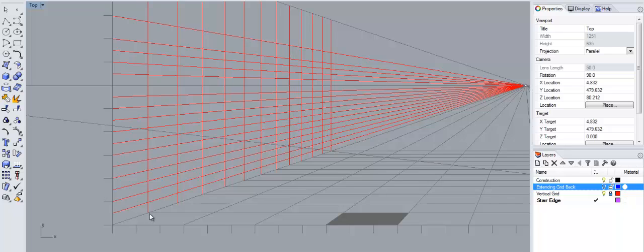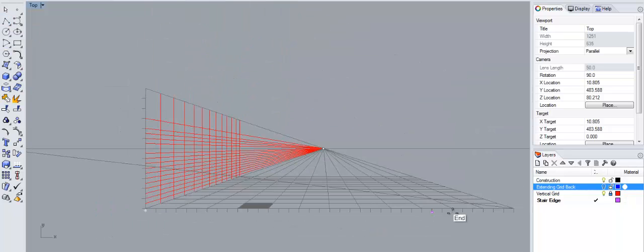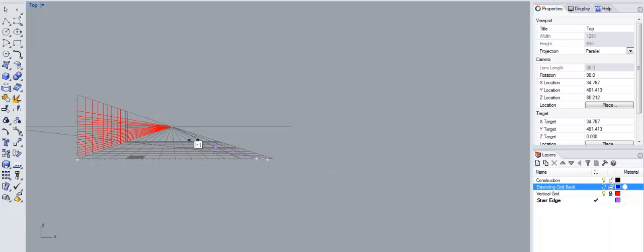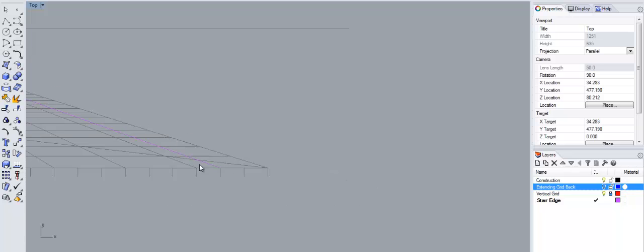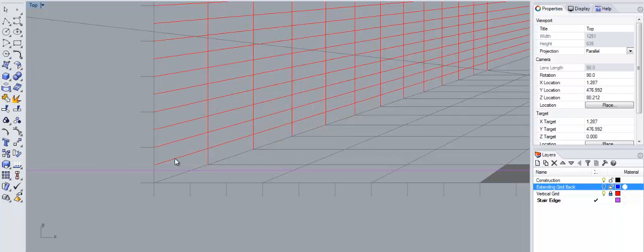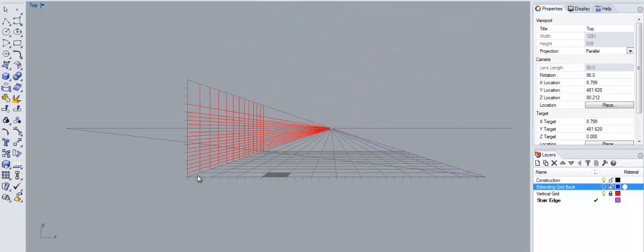So each one of these is 3 feet back, and so I'm going to assume for each one of these steps that we're going back 3 feet. It's obviously whatever it is that you measured, and you should set up your grid according to that, right? So I'm getting these 3-foot sections from going in here, and if, for example, each one of these was 2 feet, I could come over here where that intersects this, using my parallel bar. I could start to build that out, and then wherever that intersected, I could draw that up, and so that would be 6 inches up and 2 feet back. Okay, I'll go ahead and undo that.